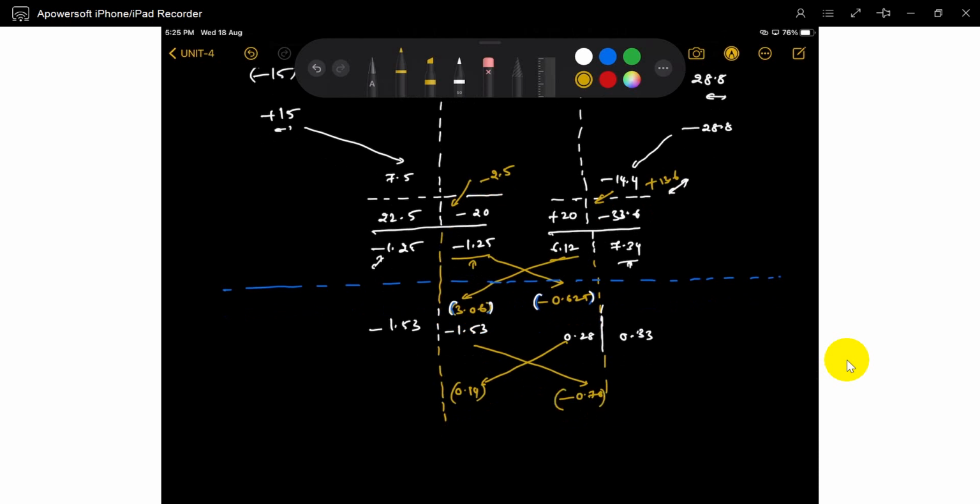This 0.76 is unbalanced at the joint. So we have to distribute it. So 0.14, we have to distribute among BA and BC. How is it? 0.07, so 0.07 minus. There's a positive extra. We have to maintain minus and minus. That's it. Now it's 0.76.